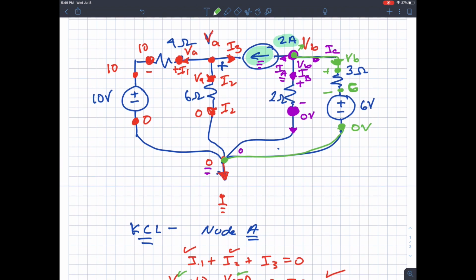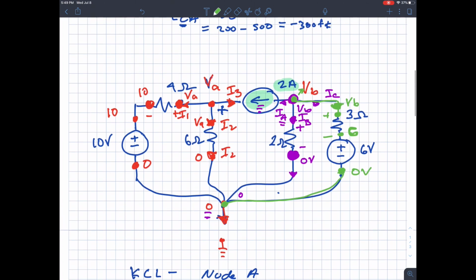We'll do more of these so that you can figure out what to do, and then we'll throw in some twists. Like you could put 2 resistors in a branch. If you put 2 resistors in a branch, what do you think you would do? The preview of that answer is if they're in the branch, they're in series, and so you can come up with an equivalent circuit and replace that branch with an equivalent circuit. We'll do more of those, and you'll see how to write node voltage equations.